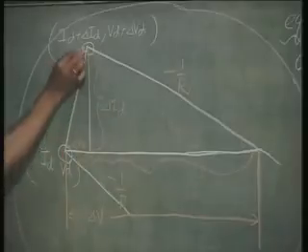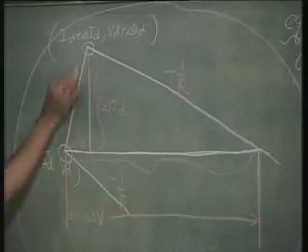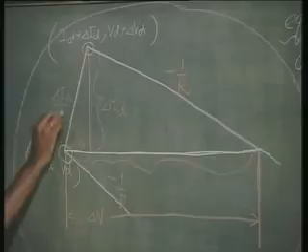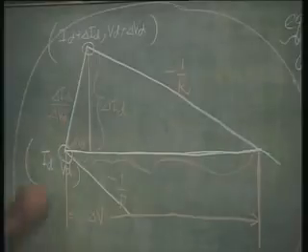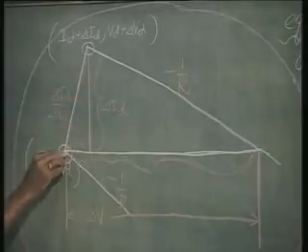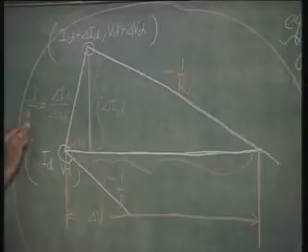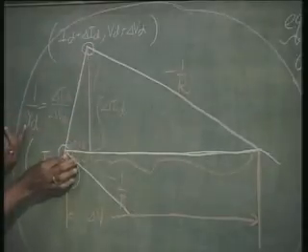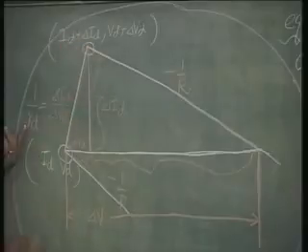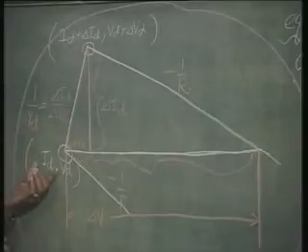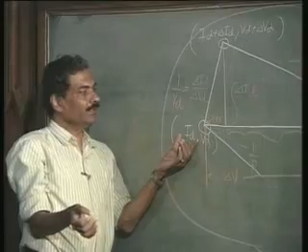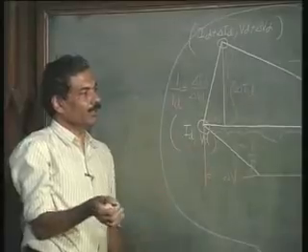So, if you assume this to be linear, then the slope here is nothing but delta I diode divided by delta V diode, which is given as 1 over R diode by us, the equivalent resistance. So, when it is linear here, this can be approximated as a resistance, whose magnitude can be evaluated as Vt divided by Id. That is what we evaluated in our analytical model.